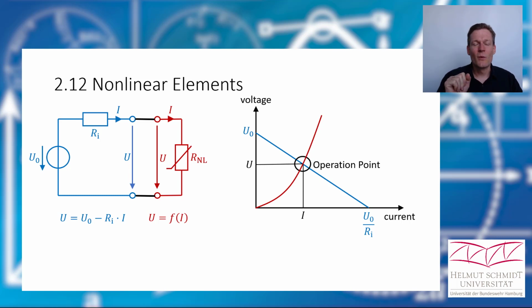So please, when you have a nonlinear element in a circuit and the output characteristic curve is given, forget calculating anything with that. When it's in a bigger circuit, then transfer the rest of the circuit into a practical source, draw the characteristic output curve of that source, and find the operation point with your nonlinear element. Never try to calculate with nonlinear elements in this class, okay?